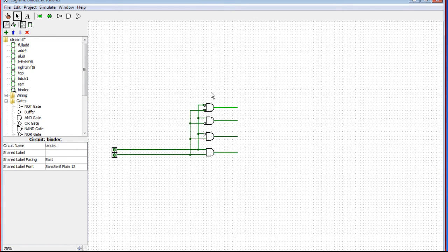Anyways, it doesn't matter. If it adds transistors, what you would do is generate at the beginning the signal and the inverse of the signal, the NOT signal. You generate them both here, and then you'd only have 2 extra NOT gates to generate all of these NOTs. But I'm just going to show it here because it's easier to inspect and just look at.